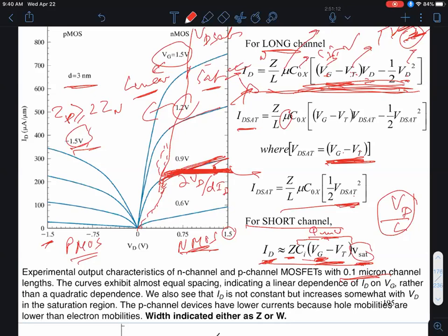Now, what is a double whammy is the fact that if I look at the source drains, in the PMOS, you have to dope it with acceptors, while in NMOS with donors. It turns out the acceptors, which are boron in silicon, unfortunately, you can't put in as many as you can donors like arsenic and phosphorus. So as a result, the source drain series resistance that I think I mentioned last time also is higher for PMOS.